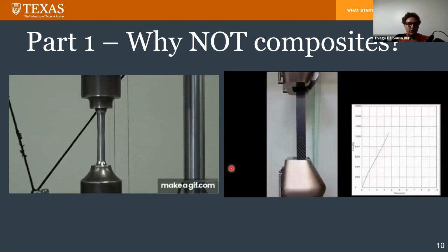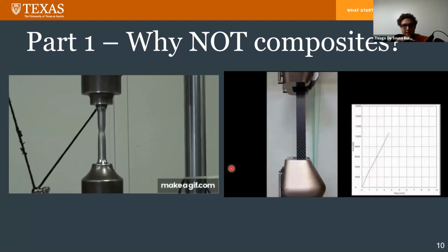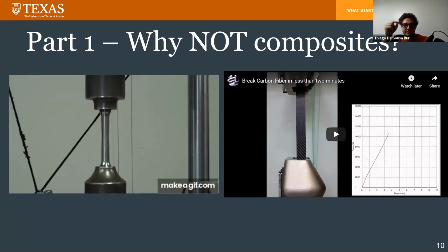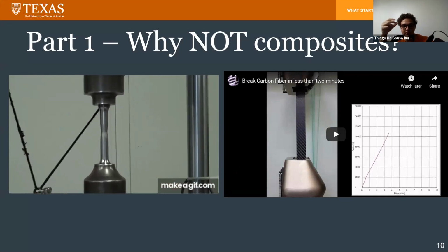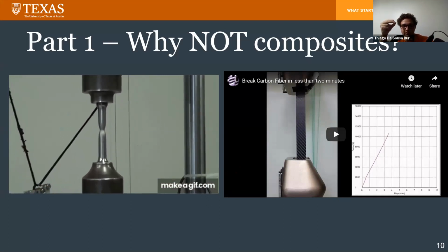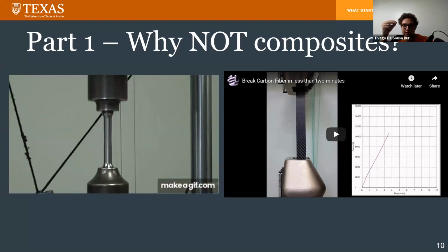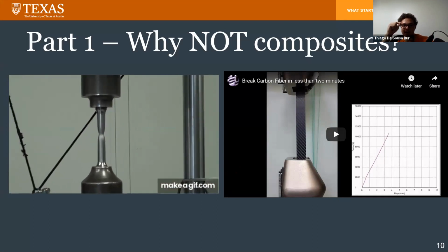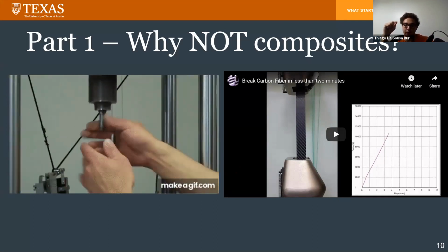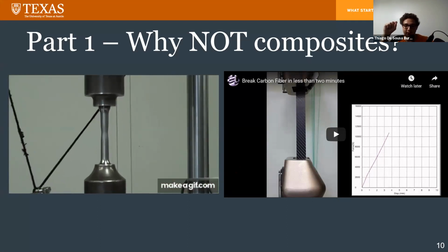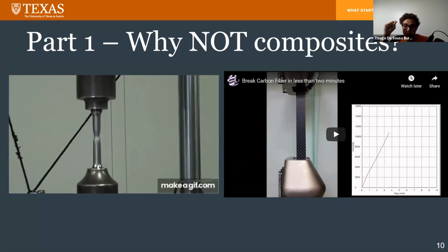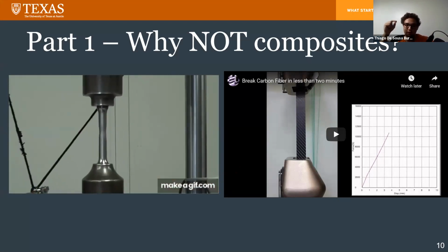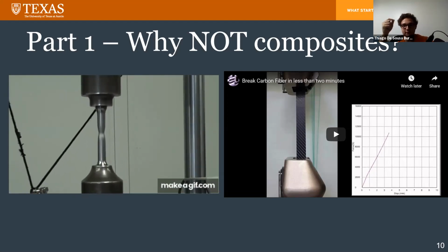And I actually wanted to show, on the left, a metal in a tensile test, and you can kind of see that necking happening. Necking is the process in which you can see the area slowly becoming smaller at the center. So if I were to crash a car and inspect the frame afterwards and it's deformed, I know it's gone past its yield strength. I know now that I should replace it. If it hasn't, I can visually inspect it and see, none of these yielded, I'm probably good.